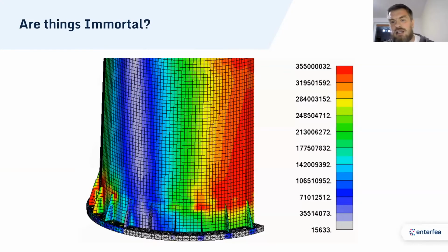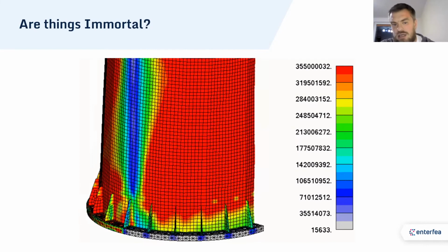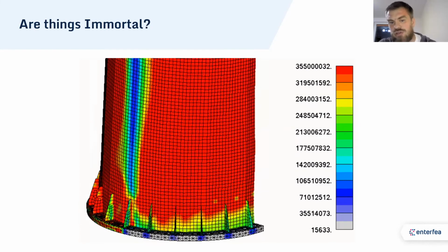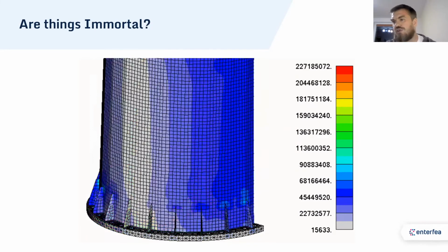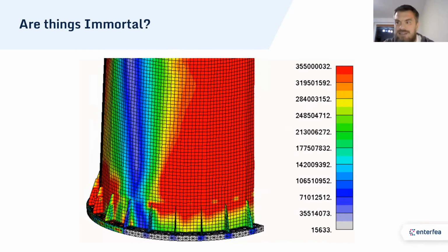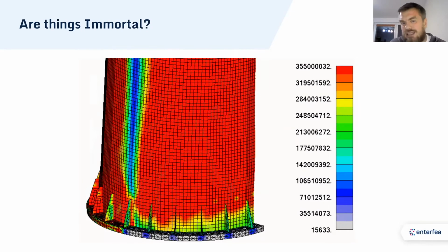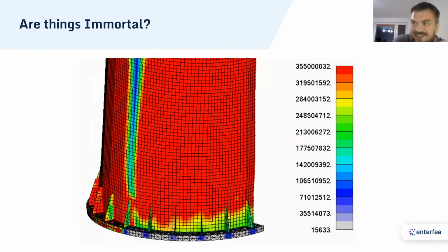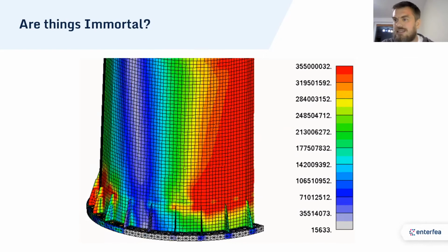Firstly, this is a model I really like. This is what you can get in a nonlinear FEA. If you use nonlinear material, notice that if I had sufficient computing time, I could literally yield the entire model. You can even see how the neutral axis in bending is forming in a straight line. This is where the bending doesn't happen because it's a pure bending case, right?